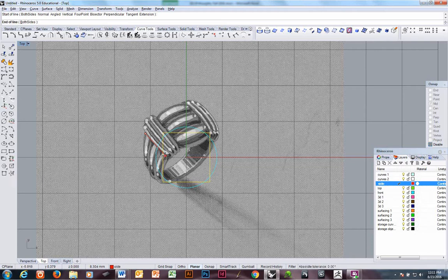Okay. Now a trick I use with 3/4 views sometimes is that since I see the front edge of the piece here, this is once again partially front view, partially top view. In theory, if I measure the whole distance, it should be pretty close to a straight on top view, because I'm going to gain a little bit in the top view with that extra length, but I've lost some of the top view because it's been foreshortened here.